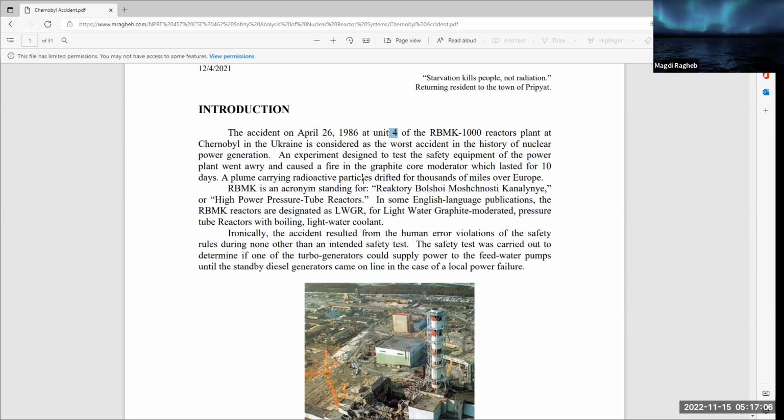That feedback is compared with the input to generate really the control signals to the reactor itself. In essence, any stable configuration for any control system has that negative sign here, meaning that the output depresses the input. And if you have a perturbation that happens to the system, you'll find that it decreases exponentially. A system of that nature is called the negative feedback effect. If you have that positive, you'll find that any perturbation of the system, say a small perturbation, grows exponentially. And in that case, the system is unstable. So all existing nuclear power plants or reactors in operation have a negative feedback effect.